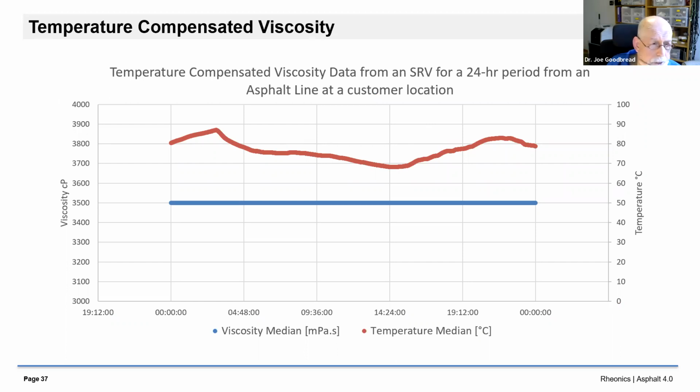A critical feature of asphalt viscosity is that it varies strongly with temperature. Hot asphalt can be mixed and pumped and transported and applied. When it cools, it hardens to a state where it can take very high loading without flowing. Therefore, a major goal in measuring asphalt viscosity is to predict its behavior at point of application from measurements taken at temperatures higher than actual use temperatures.